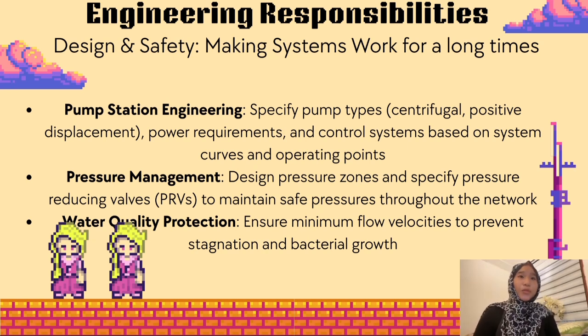So let me walk you through the key responsibilities, which is the first one is design a safety for long-term operation. So as you guys know, engineers must select the right materials, anticipate dynamic loads like wave or pressure surge, and apply safety factors. So for water system, this means specifying the correct pump type based on system curve and designing pressure zone with devices like pressure reducing valve or PRVs. For floating structures, it involves stability engineering, applying metacentric height calculation to design hull forms and balance.